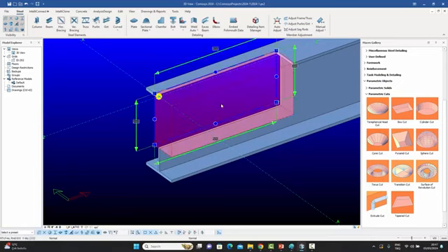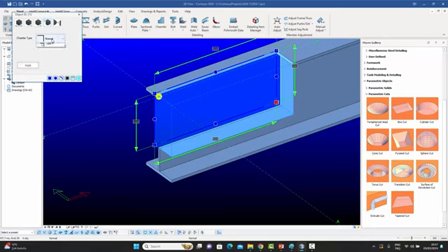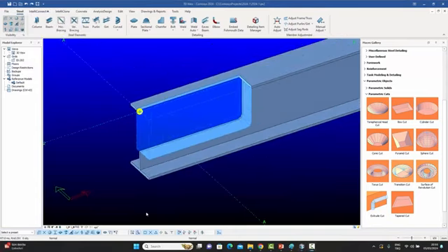But now what I have a feature over here is the definition points which I use to create this polygon cut are available as handles. And I can even insert new points in this cut. Just like you can insert new points in plates, you can insert new points in this cut. So if I were to select this point, for example, I can give it a chamfer of this type and give it a radius of say 20 and say apply. And immediately I get a little chamfer over there.